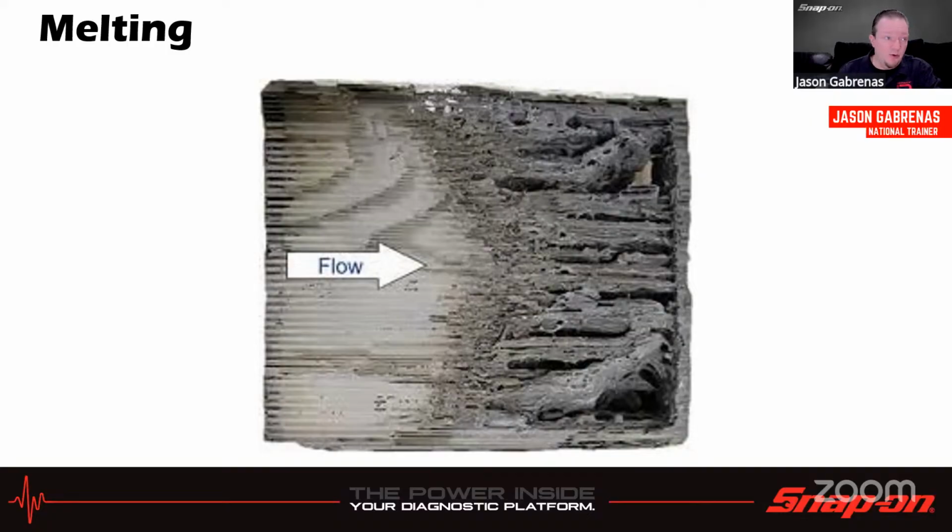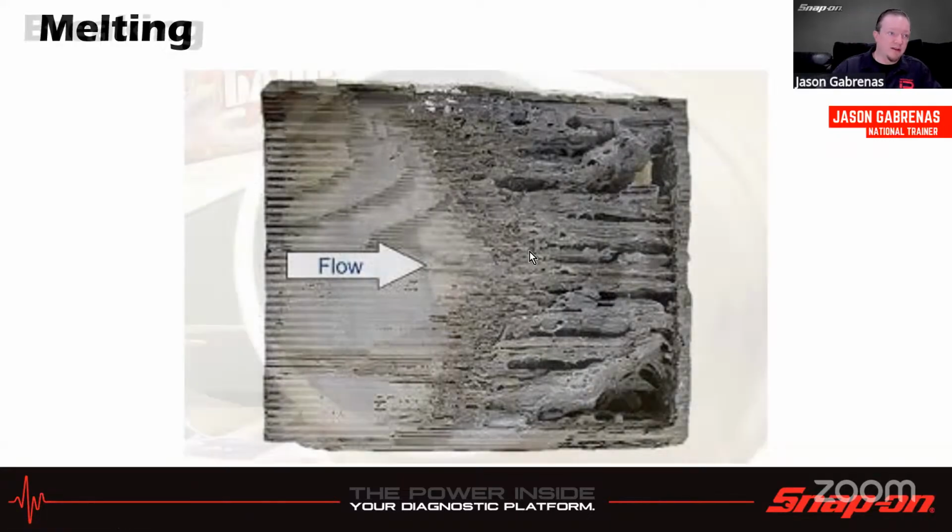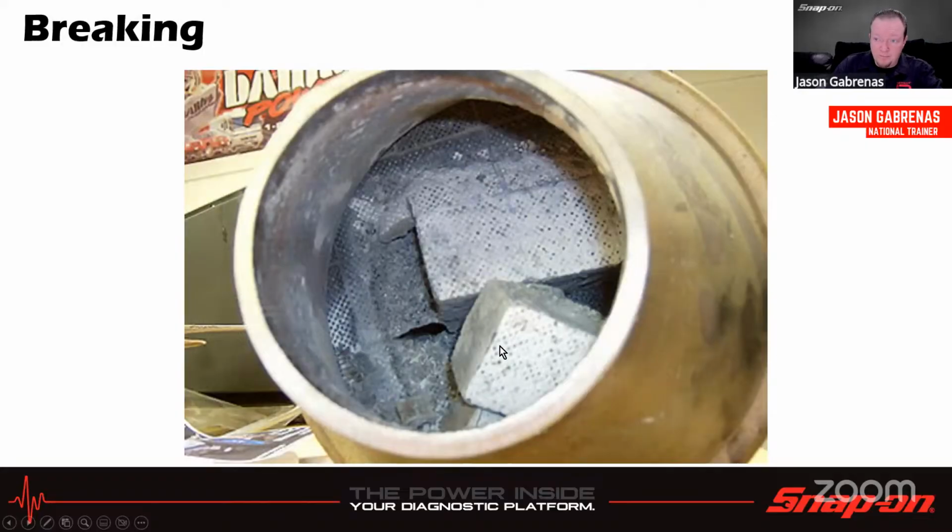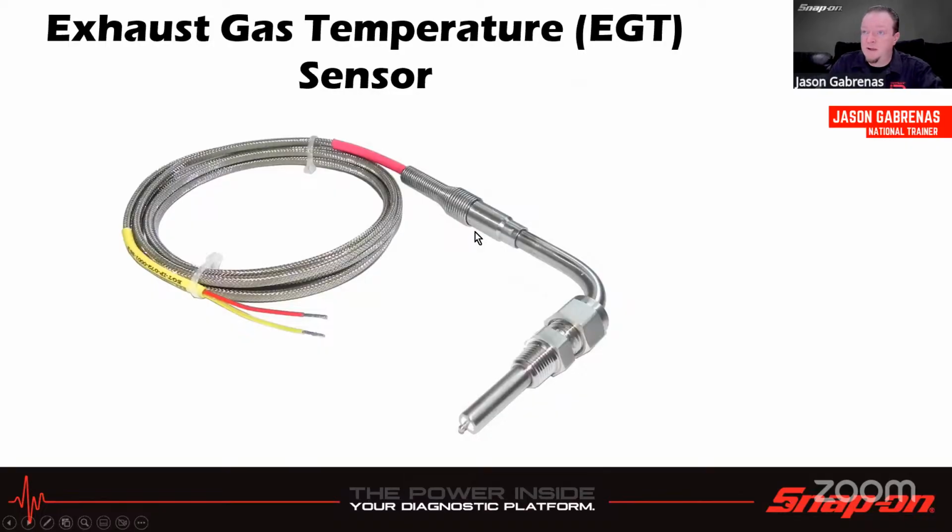If it gets too hot in there, an overheated DPF can cause melting. In this case, we got some melting and breaking. Right, physical damage in there, and in that case, that would need to be replaced or rebuilt. There are places out there that rebuild DPFs.